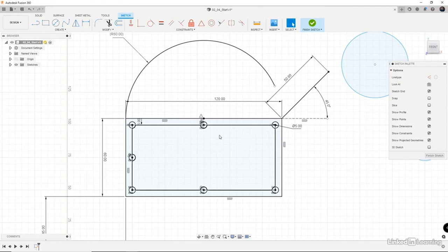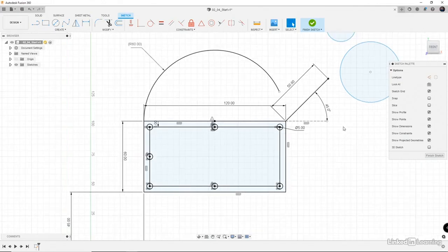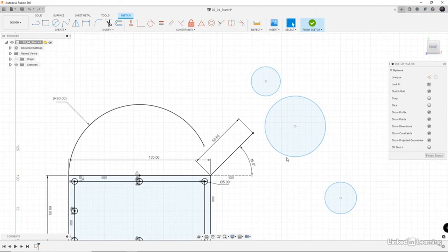This is a really easy and simple way to do that. Now let's go ahead and take a look at some of these circles over here. If we wanted to make something concentric to each other so that these were both the same center points, we simply could by using the constraint and specifying our circles. And there we go, we constrained it.